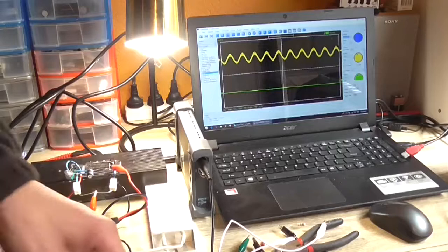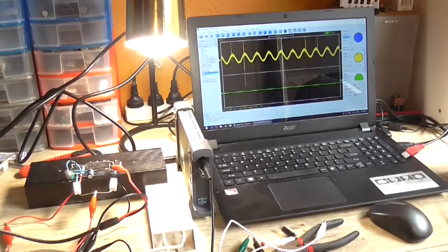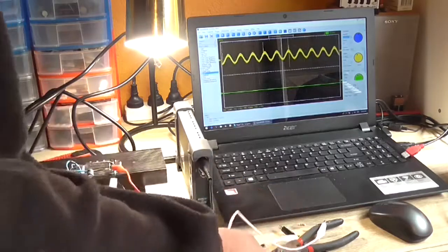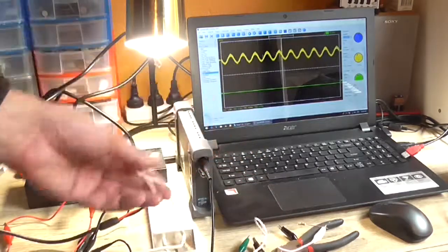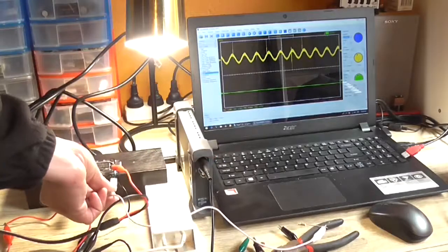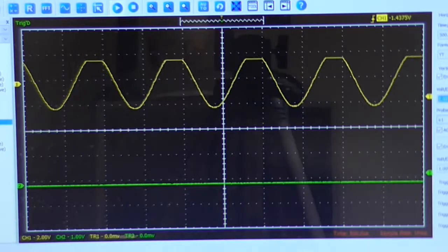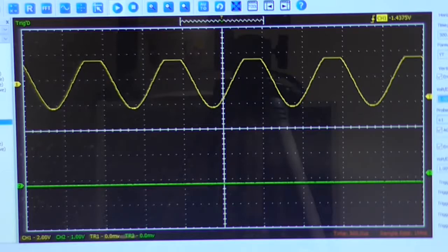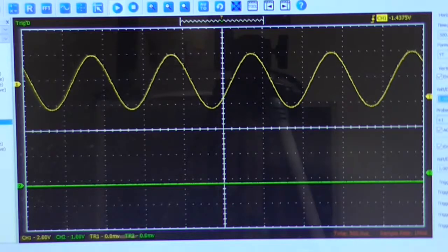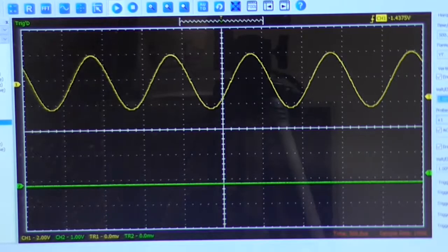So I've got the resistor and capacitor just joined with some jumper cables on the desk here, and if I take my 10 ohm resistor in and connect it to the 2 resistors, immediately we've got a nice clean signal. Now if we change the bias, we can see that we're flat topping. So the bias pot really doesn't do anything. It doesn't need to be there.